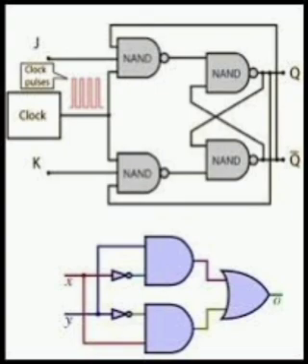TPD of the flip-flop is less than TPW and the flip-flop is level triggered. For the duration TPW of the clock pulse, the output Q will oscillate back and forth between 0 and 1. At the end of the clock pulse, the value of Q is uncertain. This situation is referred to as the race around condition. To avoid the condition, TPW should be less than TPD of the flip-flop. Race around condition does not occur in edge triggered flip-flops.